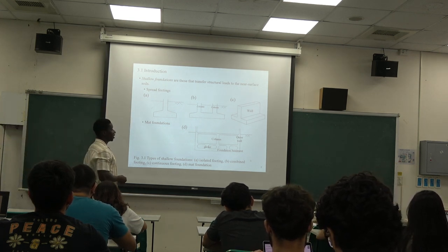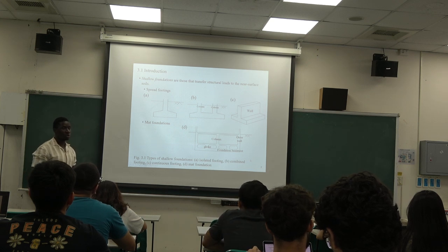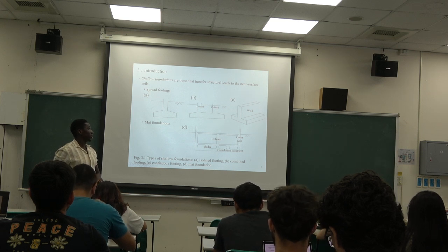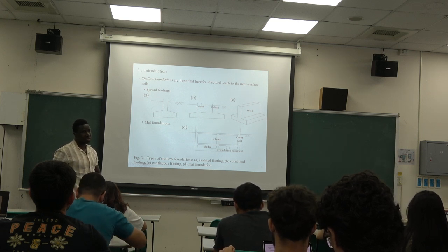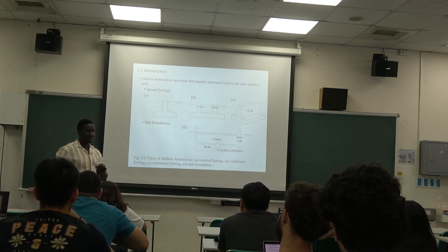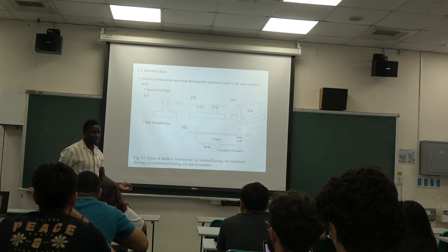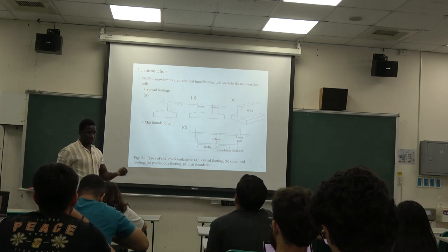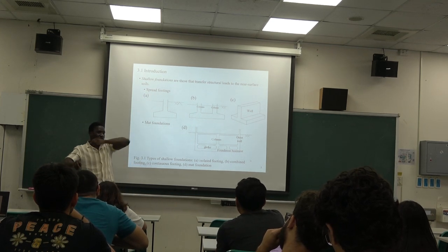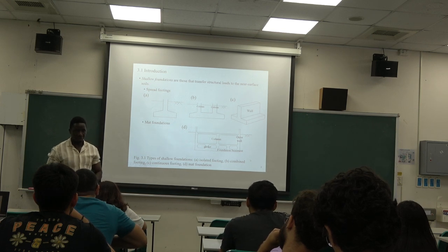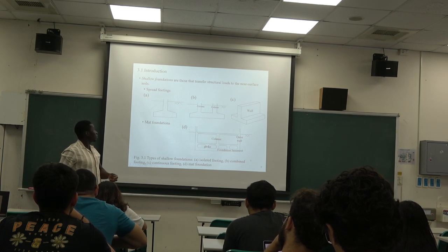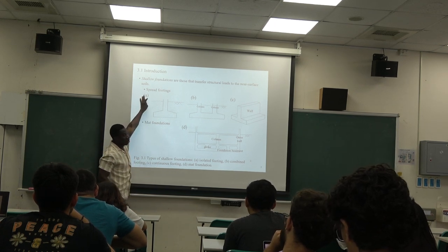The definition of shallow foundations is actually quite straightforward. These are foundations that transfer the structural loads to the near surface soils. So why do we even need foundations? Because we want the foundation to transfer the structural load to the soil in such a way that the soil can sustain the loads. If the load transferred by the foundation is just near the surface, then it's called a shallow foundation.